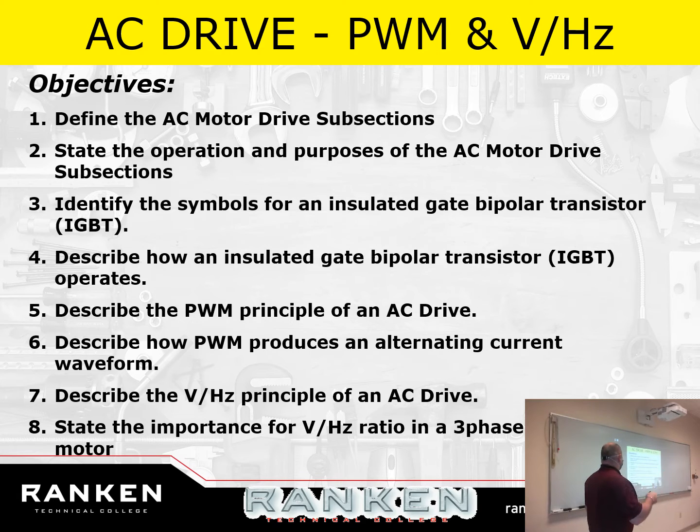So, describe the volts over Hertz principle. That's what we just did, and we're going to state the importance of volts over Hertz ratio in a three-phase motor. And the importance is you can overcurrent the motor. What'll end up happening is at lower frequencies, you're dropping that resistance to a point where you're going to start getting nuisance tripping on your drive. It's going to say overcurrent on the drive, or overcurrent, overcurrent, overcurrent. I'm not overcurrenting this drive.